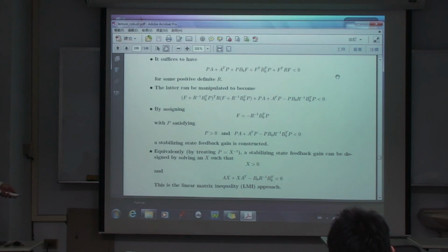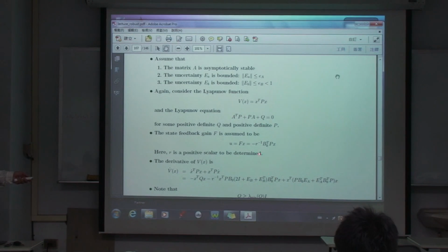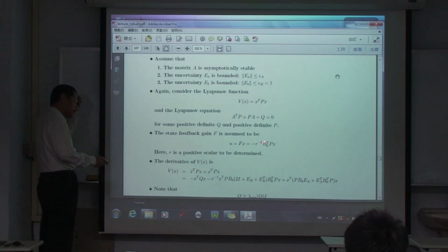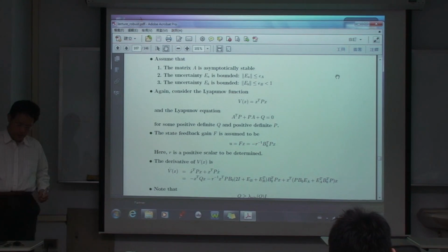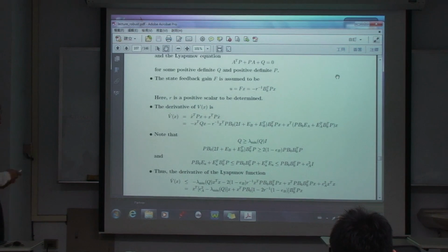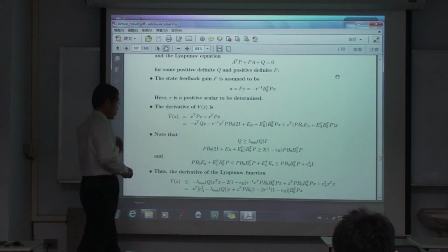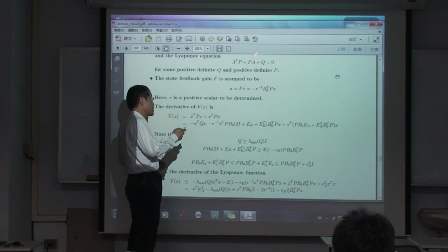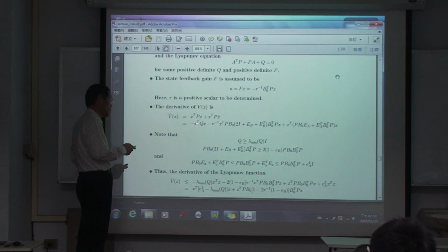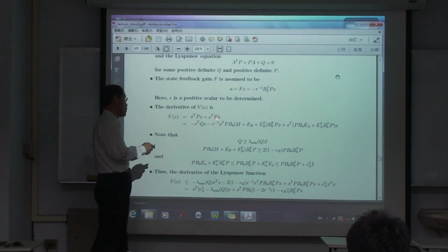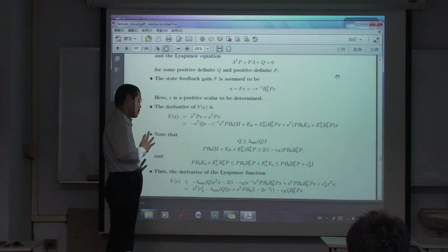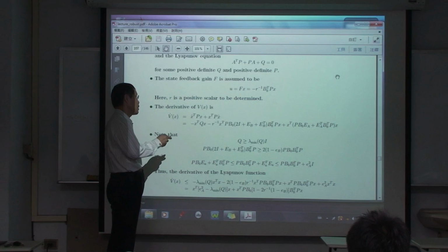similar stuff, except that I'm using a small r here, that's a matrix, for simplification. And then you could have a matrix here, but that's still okay. So I'm adopting this kind of control structure as we had talked about for quadratic stabilization, and I hope that this particular diagonal function is still applicable. If I look at this equation, I will end up with this kind of expression. It looks a little bit complicated, but that's essentially just substituting this term in that.